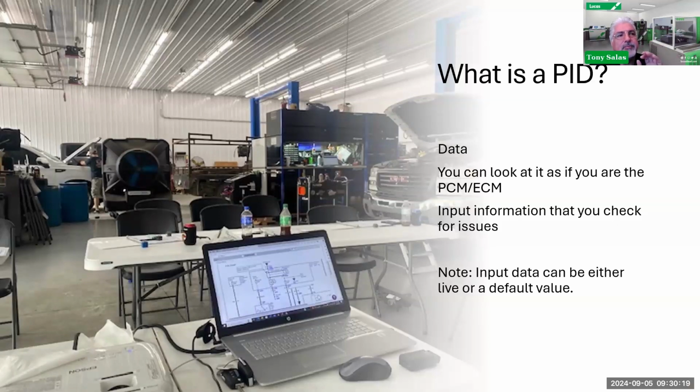Now, I know what you're going to come back and tell me. Well, Tony, it ran the reductant fluid quality test. Why did it allow it to run with the engine so cold? Well, there's a flaw in the program. Ta-da! But that's where you come in as a tech. So again, I saw the temperature was too cold.